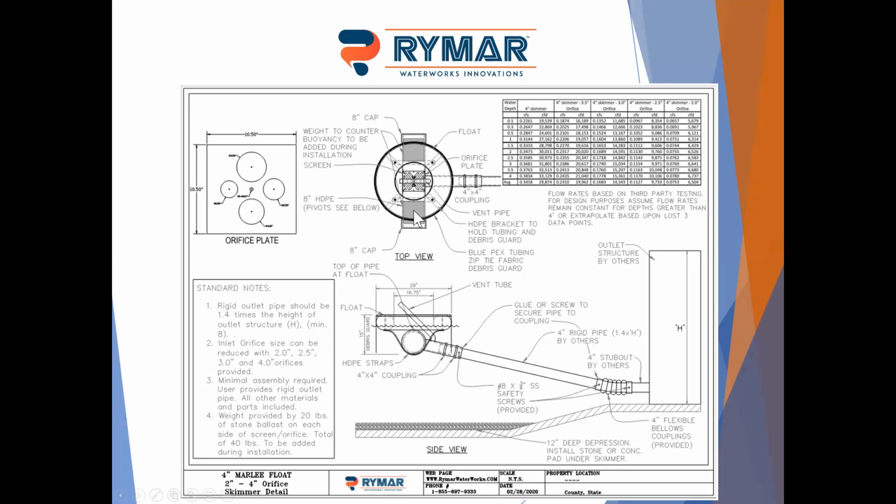Our skimmers come weighted. This bottom section here, you see in the top profile, either side of the orifice has stone ballast in each side of the skimmer to make sure the skimmers stay down. As you see, our orifice and this entire pipe are below the water level. Once the skimmer starts flowing, that pipe is probably only 10 to 20% full of water. So the air is very buoyant, wants to lift the skimmer up out of the water. To counteract that, we provide the ballast, but then also to make sure it doesn't sink, we've got a float on top to keep it level and at the right elevation.